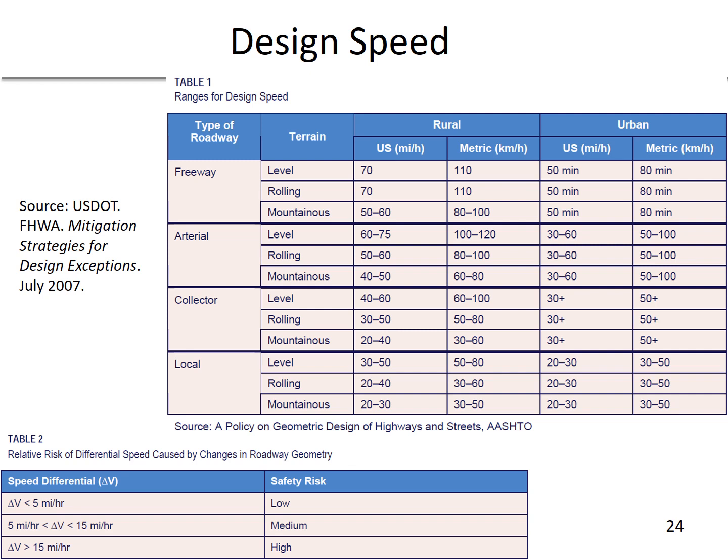The design speed can differ on different segments of a project, although consistency is very important, and there's lots of new tools to help us establish and identify where we're going to have disruptions in consistency. And drivers, particularly local drivers, will begin to learn and know the design speed of a road. If you think about a road you're familiar with, you will tend to know what curves are able to be traversed close to the speed limit or much under the speed limit, and gain that real sense of what the design speed of the roadway is. So on roads that you're familiar with, you're going to develop some intuitive perspective of that actual design speed.